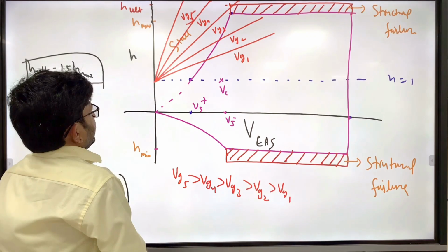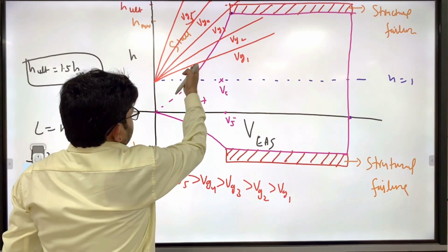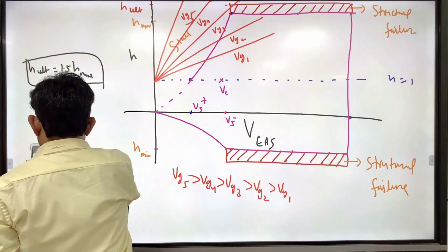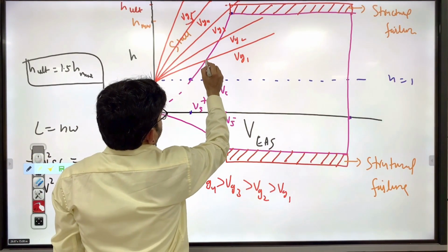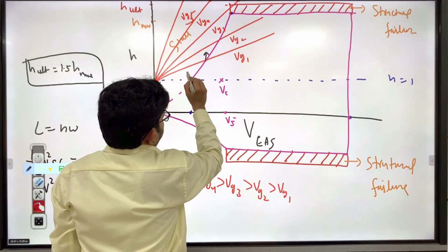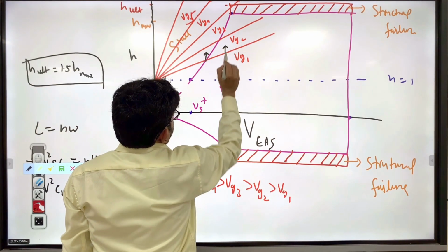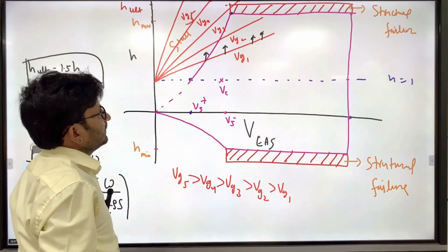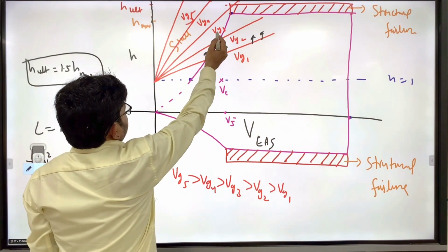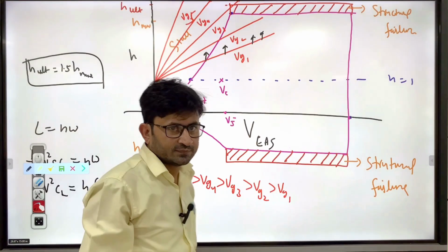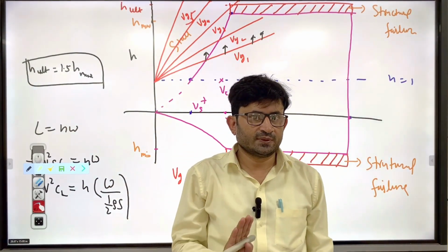So although you are inside the envelope, let's say if you consider this point, you are flying, suddenly gust comes and you are out of the envelope. But if you increase the speed, you will be inside the envelope only. But here in this case, whatever you increase the speed doesn't matter, you will be out of the envelope only. So that you have to keep in mind.